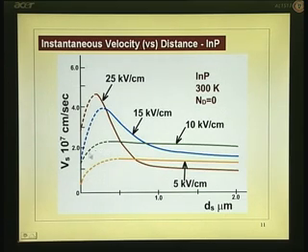In the sense, you can get benefits with indium phosphide even with slightly longer channels, even when the field is quite high. So, ultimately what we conclude is, if you take gallium arsenide and indium phosphide, the mobility of electrons is high in the case of gallium arsenide. So, low field performance will be much better in the case of gallium arsenide, but when you go to high fields, you can expect the performance of indium phosphide to be better. But technology has developed much more with gallium arsenide.